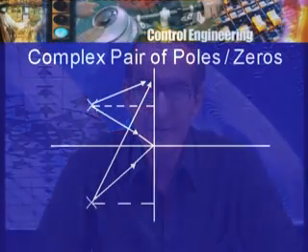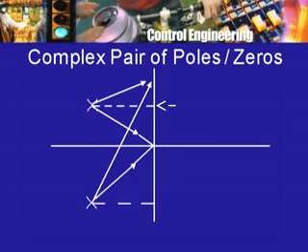What is going to happen in between? In between, of course, the phase shift will go through various values like 10 degrees, 20 degrees, 50, 90, 120 and so on. What will happen at the corner frequency? Suppose this is the corner frequency. Now, what is the corner frequency? Corner frequency corresponds to the distance of the pole from the origin.